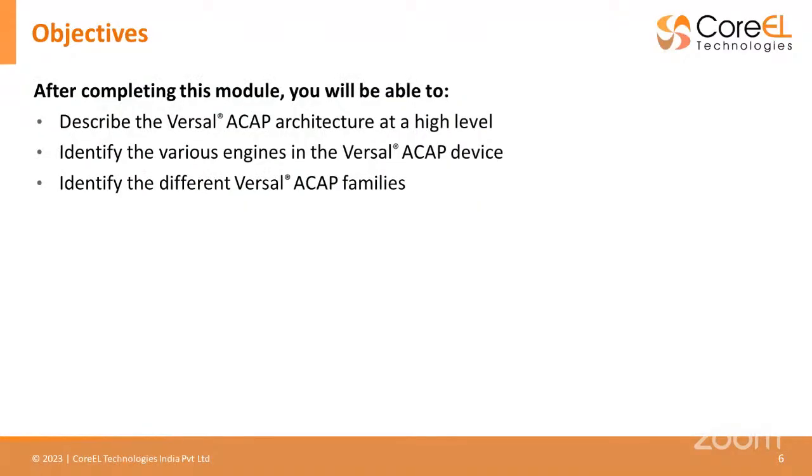When we talk about Versal, the architecture is the highest level, and you have something called engines for various purposes. Okay, similar to how we had dedicated resources in the 7 series architecture, where you have your pure FPGA, wherein you have your CLBs, your logic blocks, and then you have your dedicated resources like memory blocks and your DSPs.